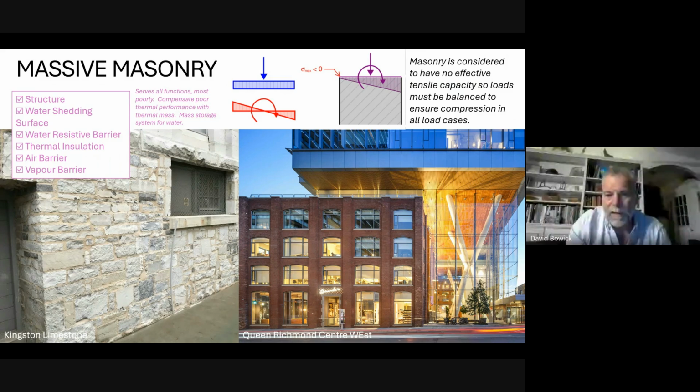This is a storage system like the thermomass. So you can see that a massive masonry wall has no rain screen and no drain cavity, and yet these walls have historically performed reasonably well. A thing that we need to be sensitive about, though, is that they rely on heat loss for drying. The heat from the building migrates out of the building, carrying the moisture with it. And that's what preserves the wall. It keeps it dry over time.